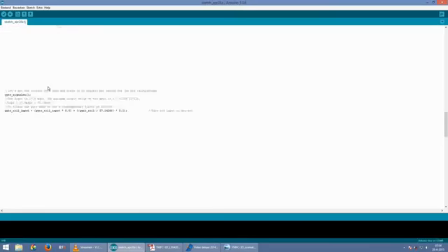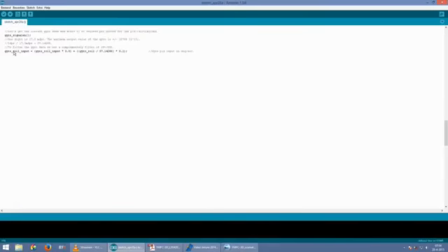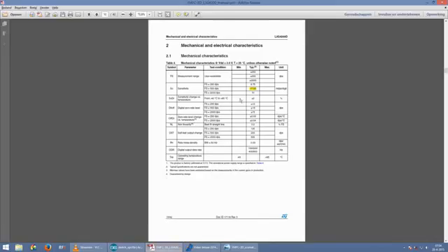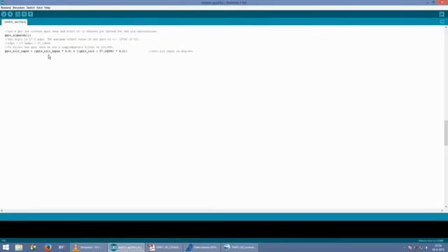As discussed, the gyro and receiver inputs are in degrees per second. In the manual of the gyro, we find that 1 bit represents 17.5 millidegrees per second. This is when we use a 500 degrees per second full scale. Because we need degrees per second, we have to divide the gyro roll output by 57.14286. To get better results, we use a complementary filter to reduce some noise from the gyro signals.